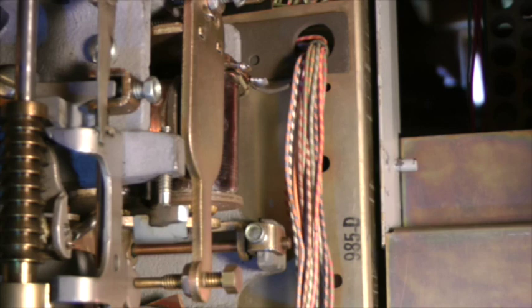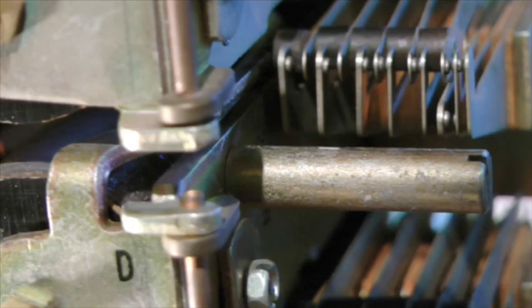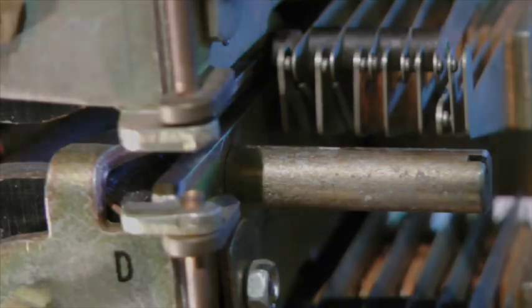The release of the VON springs de-energizes the release magnet, and so its armature releases, permitting the double dog to re-engage with the vertical and rotary ratchet teeth. The release of the VON springs de-energizes the primary winding of the D relay. If the secondary winding of the D relay is not energized, the D relay releases. The line finder is now idle and is available to serve new dial tone requests.